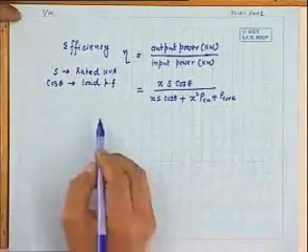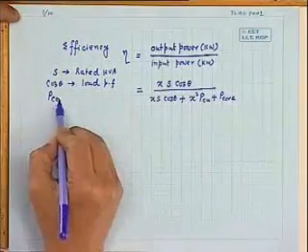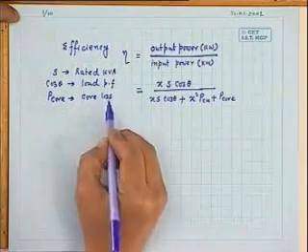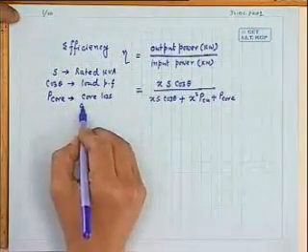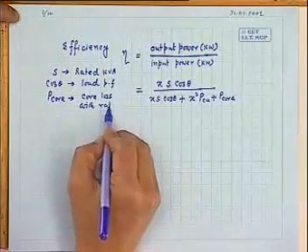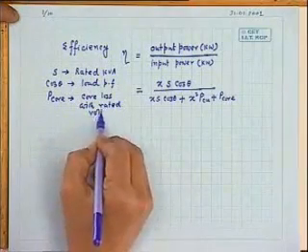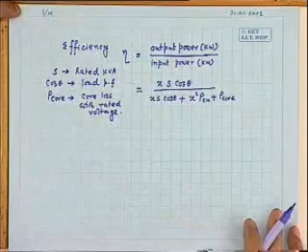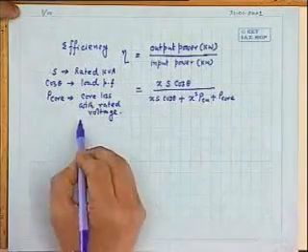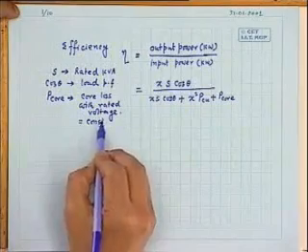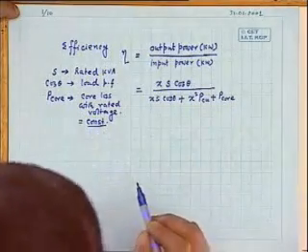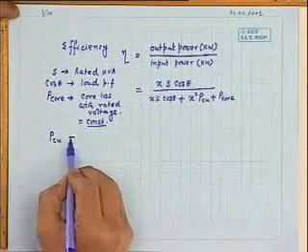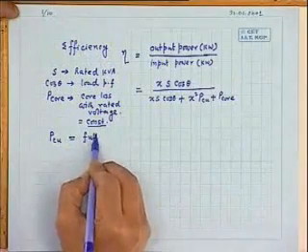And also you recollect that P core is the core loss with rated voltage applied. This core loss remains constant from no load to the full load condition. It does not change. So it is basically constant. Once the transformer is loaded, it does not change. And remember also that PCU is the full load copper loss.